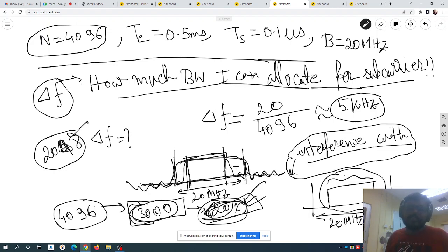So what is your question? How can I use the bandwidth effectively? Yes, sir. In this case I have no option to use the bandwidth effectively, but I am not wasting my bandwidth. It is my constraint that it says you cannot use all the bandwidth, it is 20%. Okay. For that purpose, sir, I think we use other waveform technology, filter bank multi-carrier, FBMC, that gives better spectral efficiency.